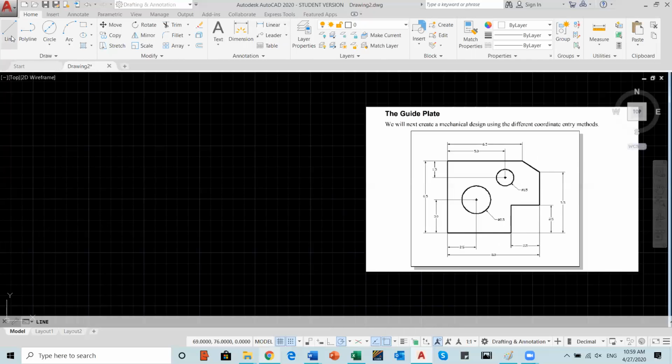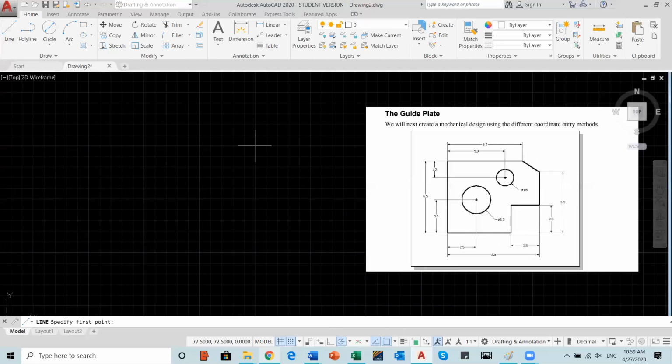Now let's start a line. I'm gonna start from here. And we need to go 3 points. I know that each square is 0.5, so I need 6 squares. So I'll get that one here. Now I go to the left, I'll count the squares, and it's jumping using the snap. I need 2.5, so this is 5 squares.